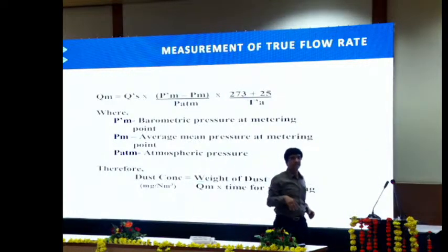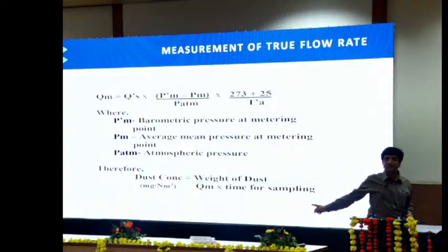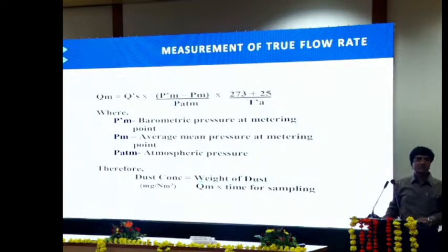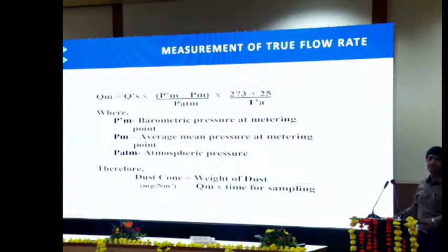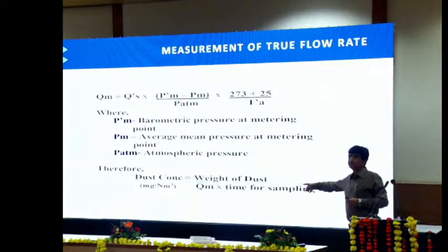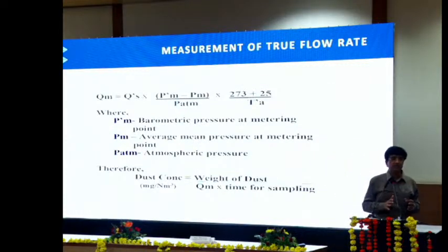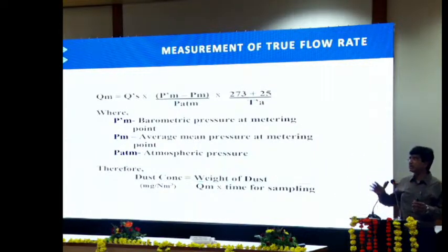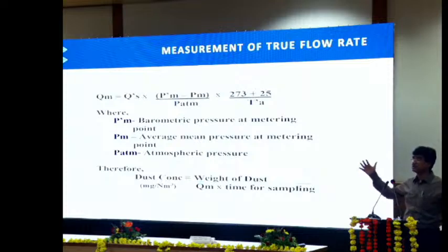Now why has this whole exercise been done, to find out this dust concentration? Now this dust concentration, what is the requirement? What will you do with it? Why did we do this particular exercise? See, the PM CEMS calibration is based on this value. So what is required is, whenever you are doing the manual stack monitoring, you need to run your CEMS also simultaneously.